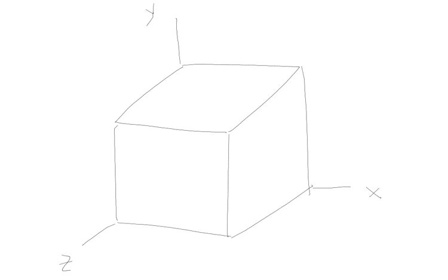All right, so let's start with this face. This was sigma x, right? So here's how we're going to do this. If I take a look at this shear stress, it is in the y direction, and it is on what I'm going to call the x face. So what is the x face? The x face is the face that's perpendicular to the x-axis. So this is what I'm going to call tau xy. It's the shear stress that's on the x face, in the y direction.